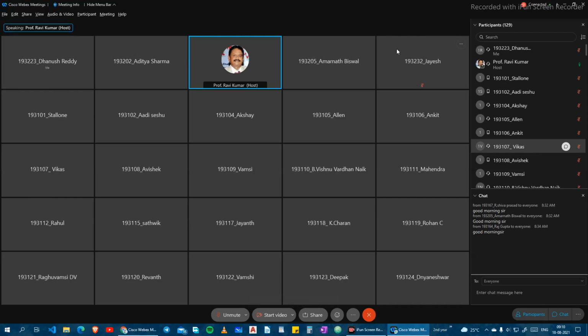And if you see practically, go to any mechanic shop and see the piston, the crown shape will be different in two-stroke cycle engines compared with four-stroke cycle engines. But for four-stroke, we are going to have a small bowl type, where we are going to get the combustion. But generally, we don't have a fuel injector mode. In the scavenging process, a gasoline engine is a spark plug method only. We're going to get more scavenging losses.